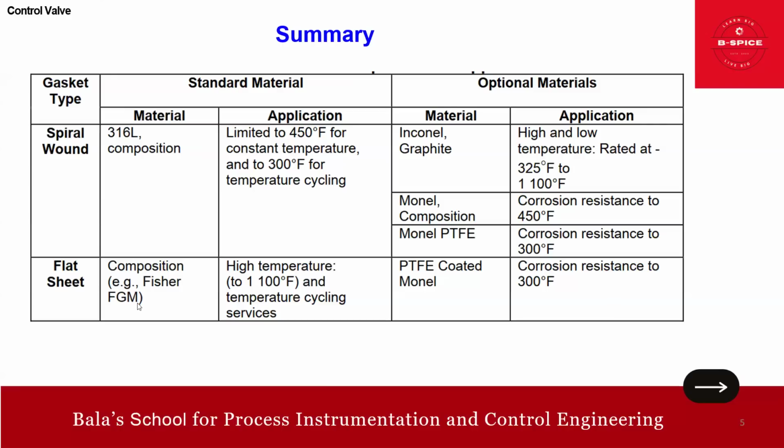Then we talk about the flat sheet gasket. A common standard for flat sheet gasket is a composition material. For example, Fisher also uses its own proprietary materials. Most composition materials are suitable for temperatures up to 1100 degrees Fahrenheit, high temperature, and of course temperature cycling services.